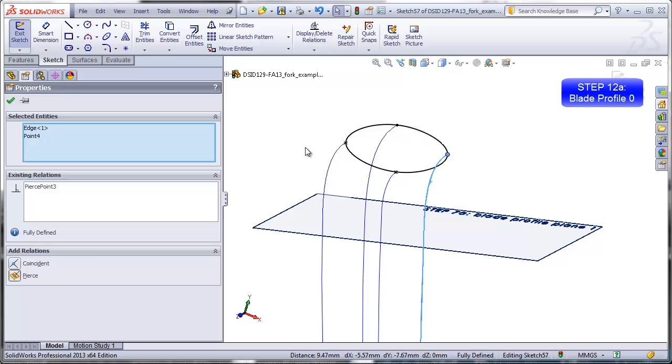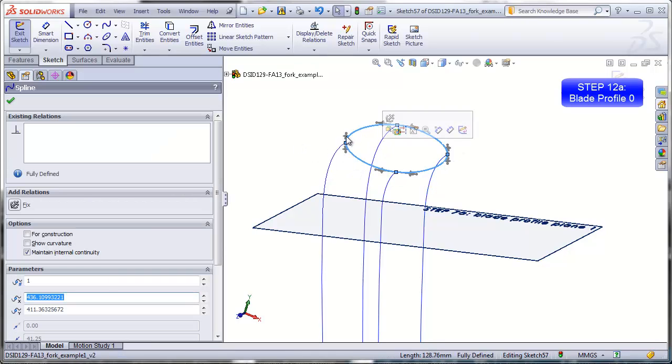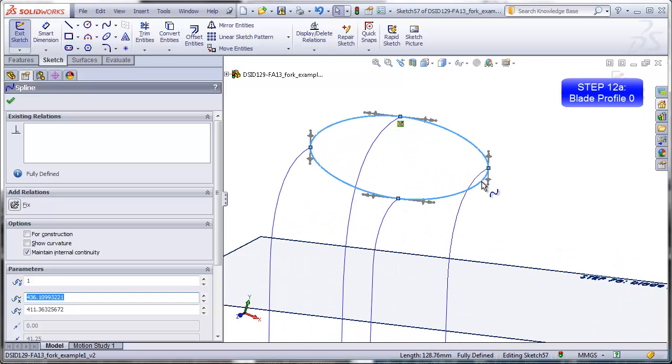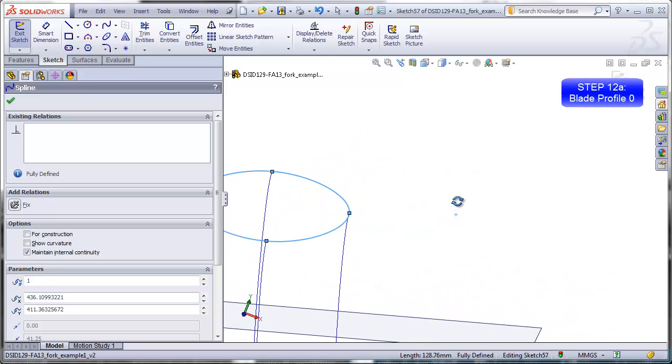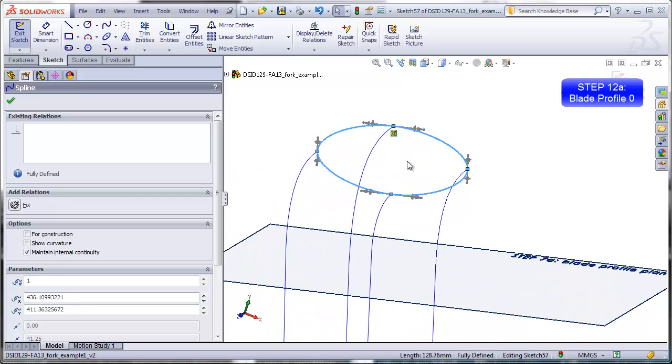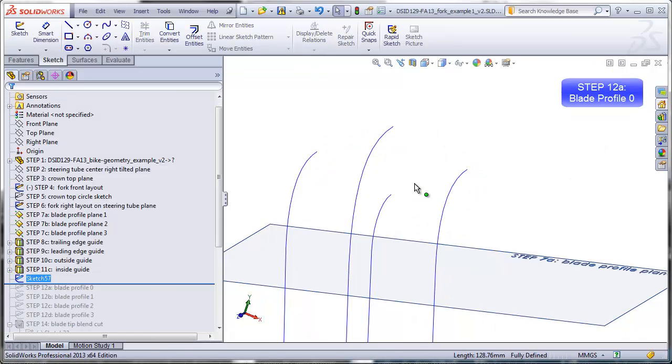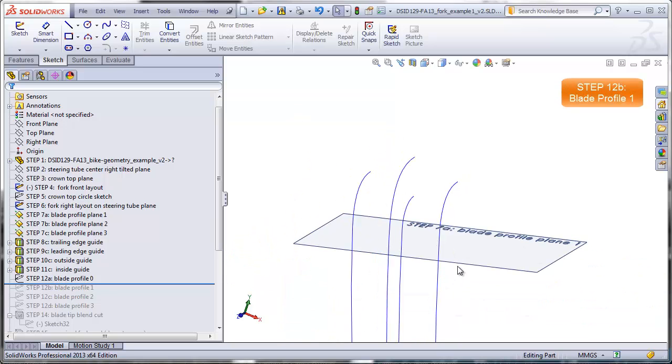This turns the entire oval-shaped spline black. And if I click on this, I see that all of the handles are going either vertical or horizontal without my having to touch them. As soon as I start fiddling with this, this is going to look non-oval shaped. So do not do anything to adjust these handles. That's my first profile. My next profile will go on this profile plane.